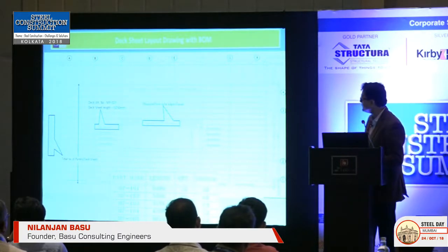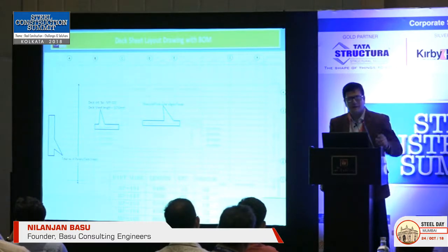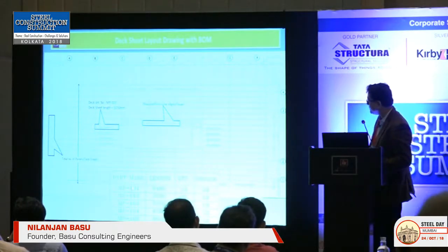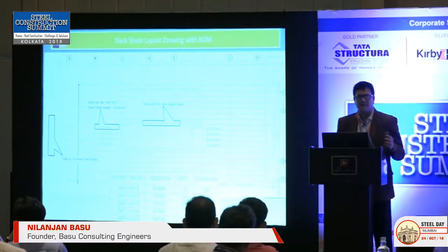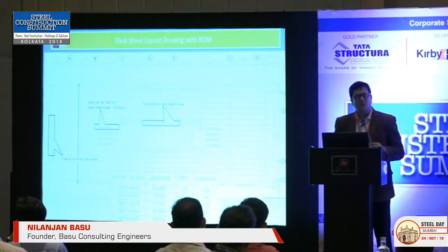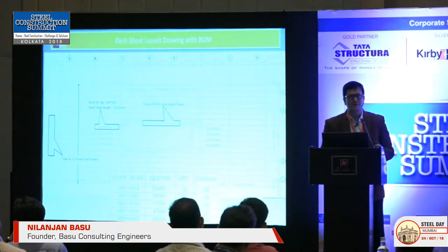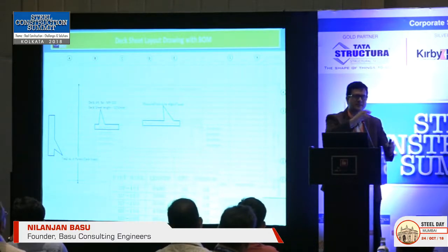It's not only on the drawing. He will send the material based on this bill of material. The MP101 has a length of 6480. It is 19 in quantity of galvanized sheet. And once he does that, you are assured with the contractor that yes, I need to place this number of deck in this place.